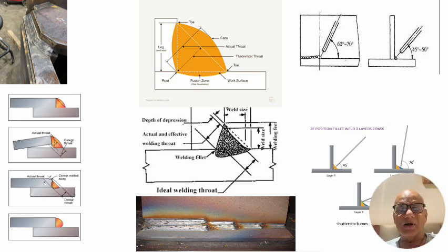So while welding a fillet, so many areas, so many angles are required, unlike in a butt joint where we have only one direction to really monitor and see that we have sufficient gap for depositing. Here there is no question of gap, because everything is open. We have to ensure that what we deposit is the right way, and if we make a mistake, not only will the fillet leg or the throat not be achieved, but there could be an excess deposition on one side to achieve the throat, or there could be a concavity, or a convexity.